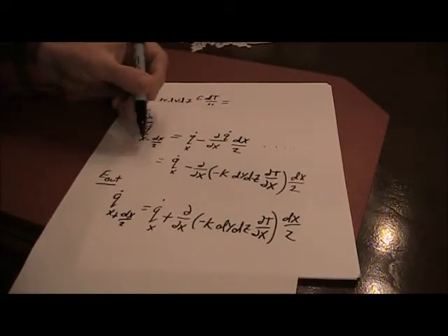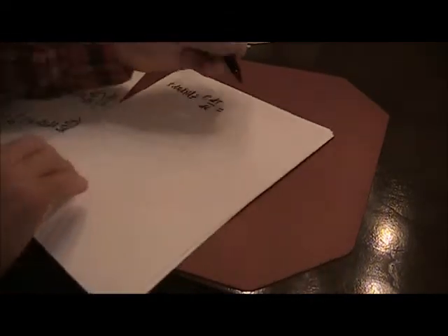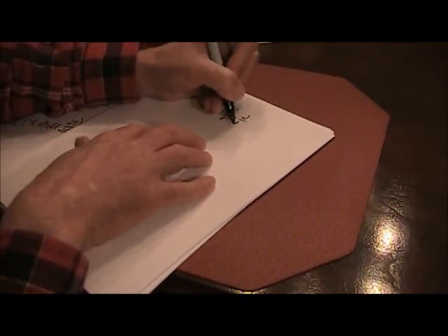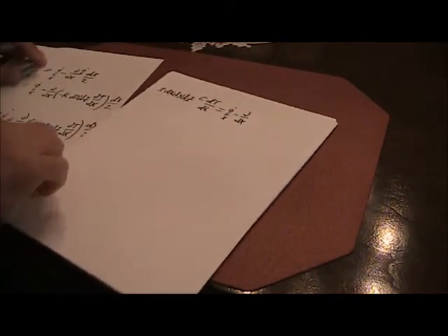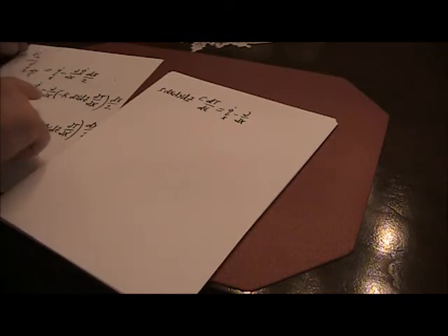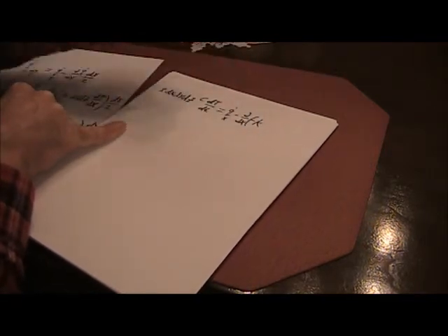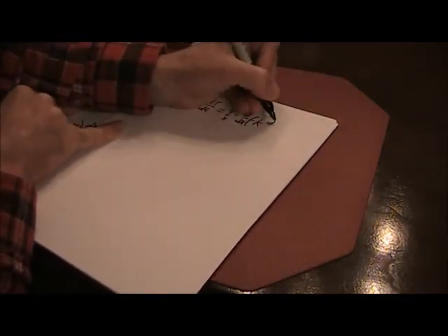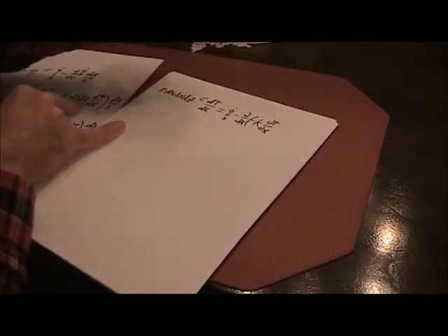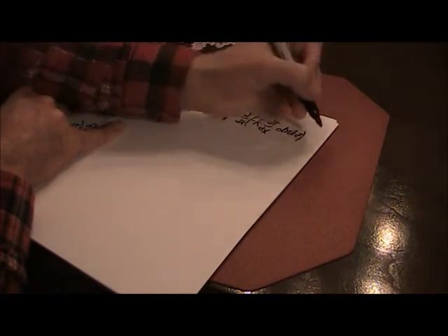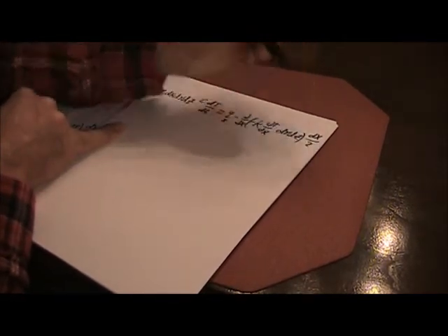Energy in was this one. So that would be Q dot at x minus the change with respect to x of minus K times dT/dx times delta y delta z times delta x over 2.